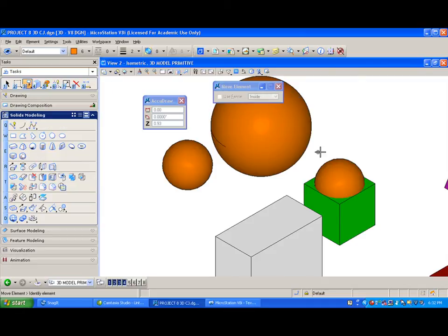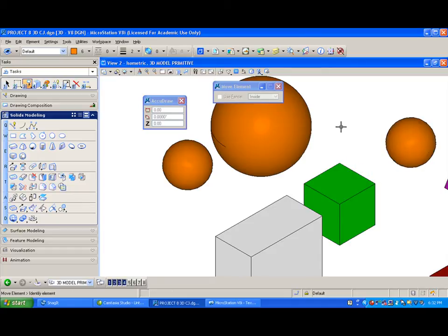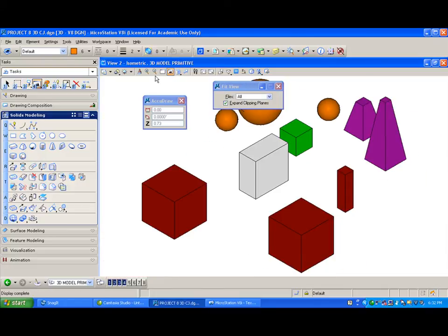And if I knew what the depth was, you can grab these just like you would a circle. So if I wanted to move this, I can grab it by the center point, hit F to move it straight up, or S to move it, well, straight up also. T allows me to move it horizontally, side to side. So if I knew it was the center, I need to move it out one, just move it out there. Again, we're using the same move, copy, fence tools, everything we used in 2D, we're using in 3D to manipulate these objects.